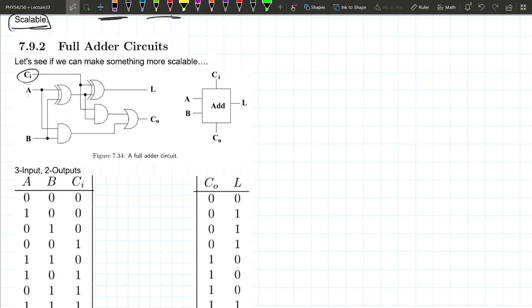Okay, so let's say my A and B are 0, my carry in is 0. I expect the result 0 plus 0 should be 0 with no carry. So let's go through that exercise just once to see what happens. If I set this number over here to be 0, 0, 0, I am hoping that this will give me the correct result. This is once again like a truth table checking. Instead of just logic gates, now we have this full adder logic.